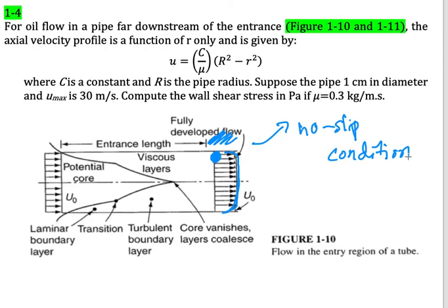That's why you will find that there is algae around the pipeline. Why could algae live happily on the surface of a pipe? Because the velocity is equal to 0. So the no slip condition is reflected in mathematical expression as u equal to 0. The velocity here is equal to 0, then it starts to develop, and then it will reach the maximum velocity at this condition.